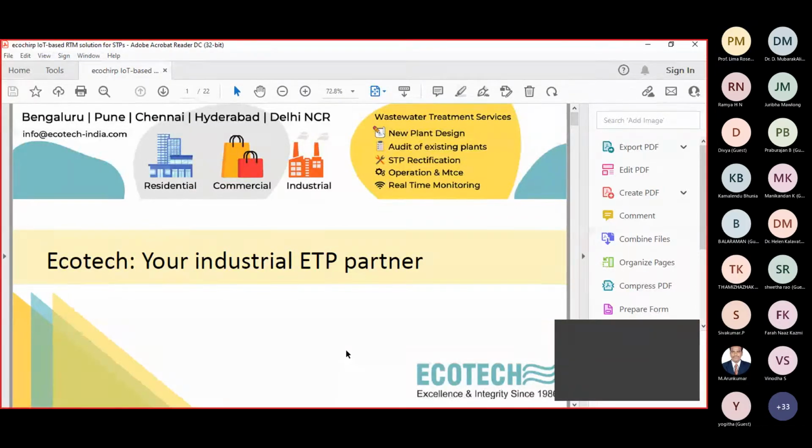Deionization only after carbon, because whatever can be removed by your biological treatment and chemical treatment, you have to remove that way, because removing anything using these membrane technologies is going to be very, very expensive. So the best thing is to remove as much of the pollutants as possible using the conventional technologies, and only then go for UF or RO for removing the final traces. So it will be like a polishing unit only. You cannot overload this. UF and RO cannot be the main treatment units.